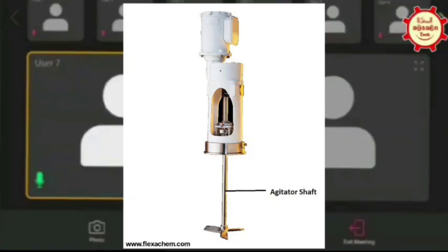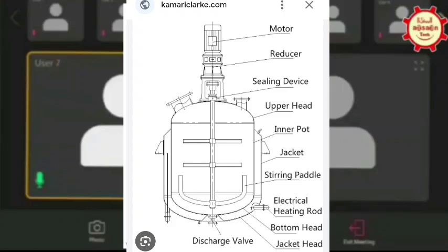Okay, Sheikh, it's your shaft, there is only an 11 mm gap you are telling. Yes, only an 11 mm gap between the bottom anchor and the bottom dish. So who decided that 11 mm? It was decided by the process team. Due to the process, they want to maintain the gap as minimal as possible. Initially they proposed 10 to 12 mm, and the vendor has provided 11 mm.